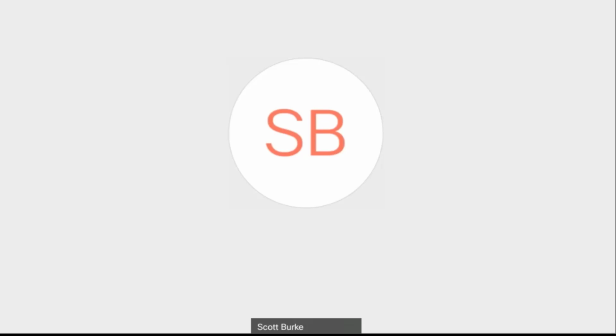And then the one that was already there that you gave a different name to is still there, and it still remembers all of its previous saved essentials, so that record is still there, which is good. So you still have all that information with that file. This is a different name. And that's basically how I would do that. So again, download, fix it up, rename the file in the existing location, and reinitiate the work sharing with the cleaned up file is the basic process, if that makes sense.